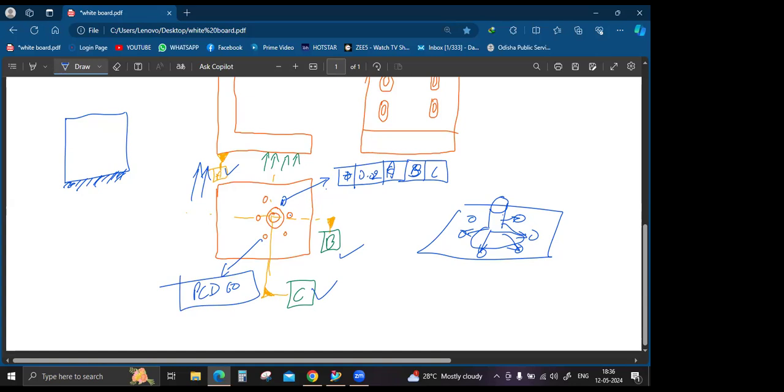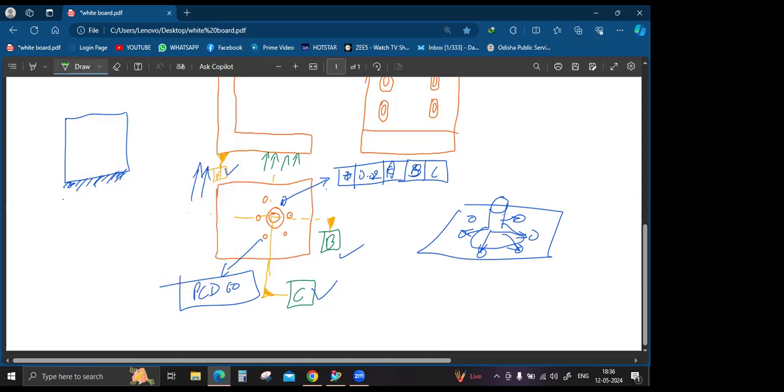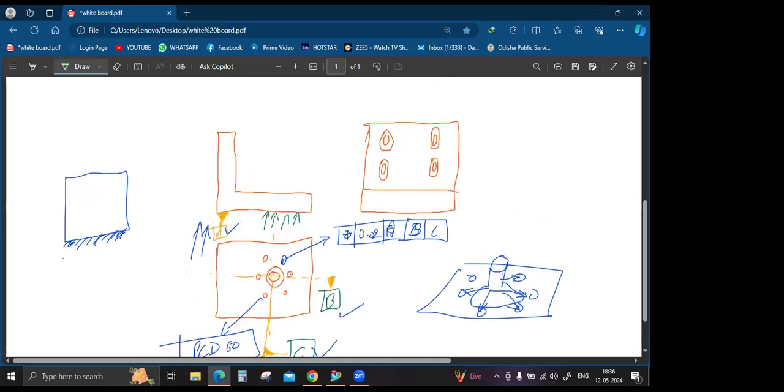Next, what tolerance can we give, sir? Whenever we are giving the reference A, see over here, sir, this A surface we are giving some length. So here we have to provide this symbol. Okay, so the surface should be plane. It will be 0.02 initially.